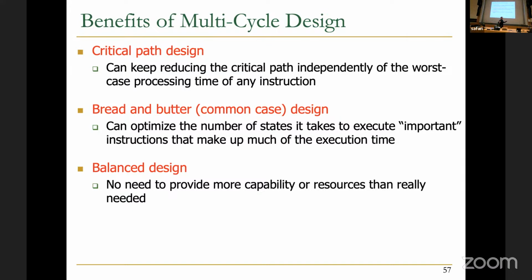Now, what does this mean? This means that you can use a single adder to do all of those 4 different additions, because you're not doing all of those 4 different additions at the same time. You do one addition in one cycle, change the control signals, do the next addition in another cycle, change the control signals, next addition another cycle, change the control signals, next addition another cycle. That's the beauty of this microarchitecture, basically.